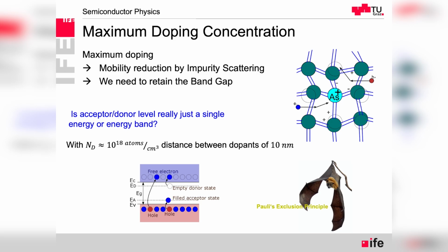So at that moment, we also have this band shifting of the discrete energy levels for donor and acceptor. They have to split the energy levels, and effectively they are going to touch the valence or conduction band, and because of that, the effective band gap that we see in the end is narrowing.